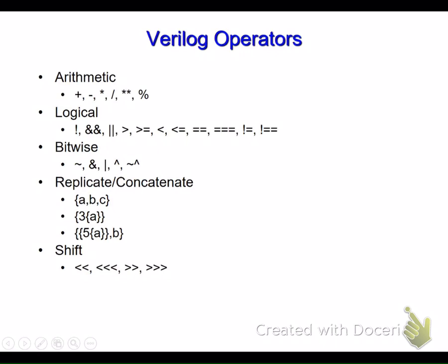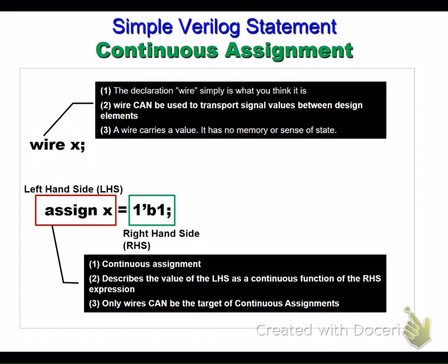With the Verilog operators, of course, you will be familiar with all of these: the arithmetic that you will need, plus, minus, multiplication, division, power, and so on, then logical, bitwise, and replicate or concatenate. We will learn all of these things. Also the shift operations, how you can do the shifts, and so on. We'll be familiar with that. Okay, so this is just the very beginning of how to write